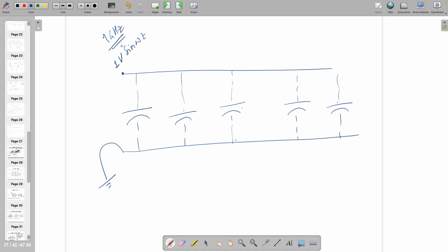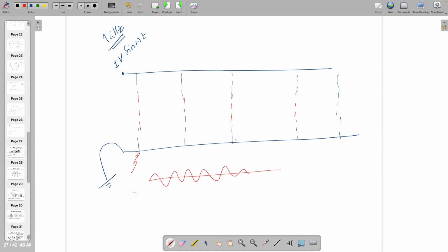So in that case, if this is a sine wave, all these capacitors, at a particular frequency, are going to be shorted with a low impedance value. Some frequency will be there where impedance is low, and it's going to get the short between that particular point and this particular point. It means this ground will not be ground, and you will see that the frequency of 1 gigahertz is reflected over here, right?